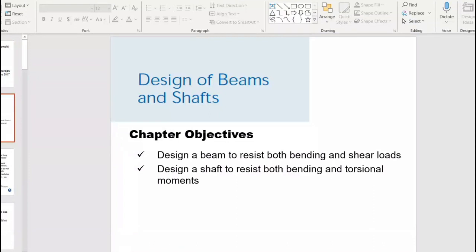Why are we not taking the non-prismatic section into consideration? They're all non-linear. It is very difficult to model or analyze them using simple arithmetic methods or the static equations that we are using. You really have to go through matrix analysis using MATLAB or software like STAAD Pro. Using software only, you can analyze the failure pattern thoroughly, and the corresponding design will be appropriate. But when you do it manually, you can only get an approximate value.